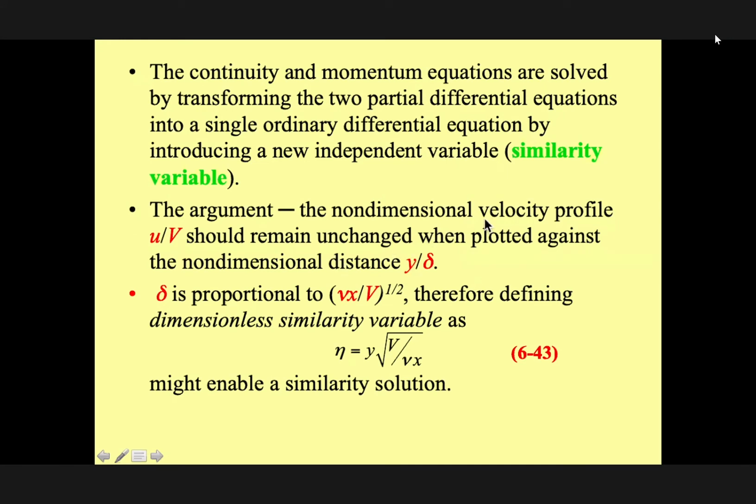If I use the non-dimensionalized form, the same thing that we did in conduction, and I find a solution, the solution is no longer a function of a specific temperature. The solution can be applied to any range of temperature. Therefore, we non-dimensionalize and try to find a general format. This has no dimension and this has no dimension, okay? Therefore, we are trying to do that.